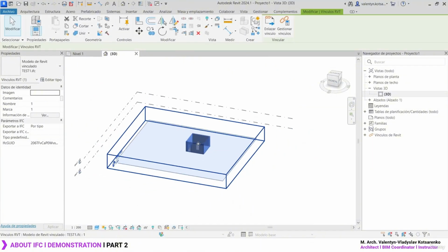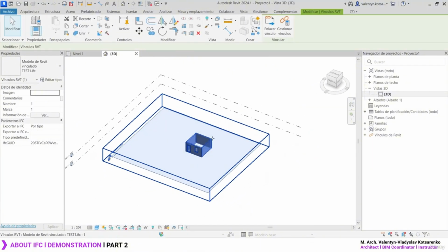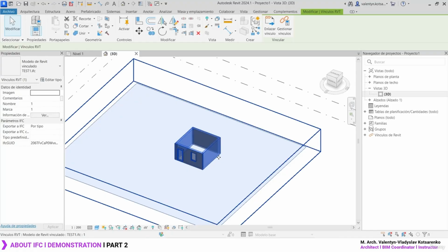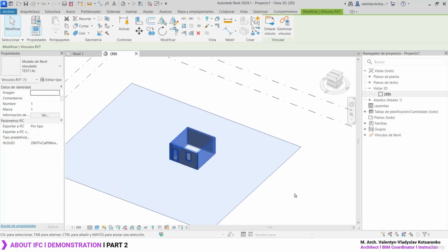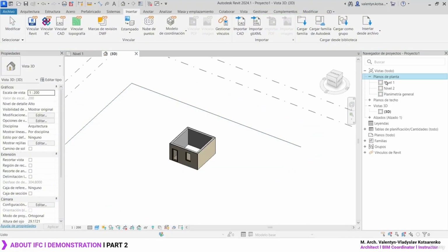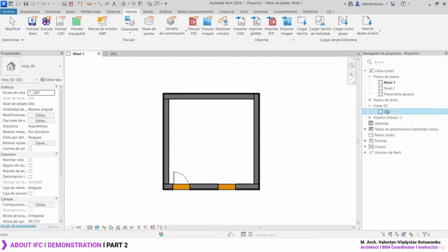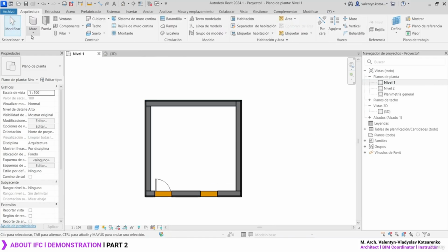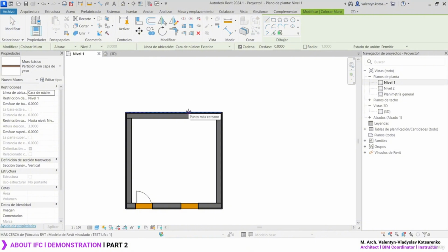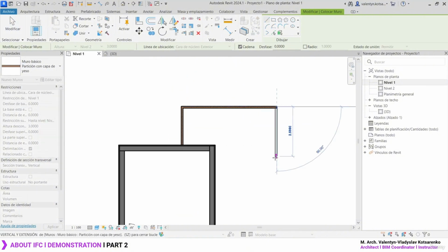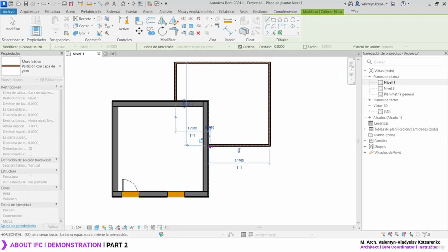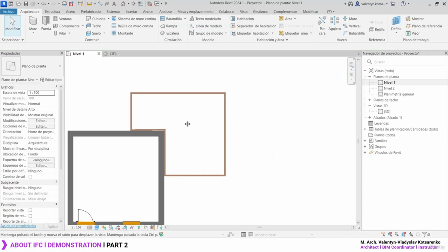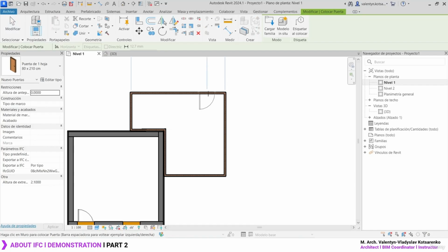It's going to also manage everything as a single element. Now this also depends upon the different translators, but at least I'm able to visualize the 3D model in my own personal platform, Revit. And now what I can do is, for example, let's take a wall over here and model an extra volumetry based upon this element. Let's create a door over here and another door over here.